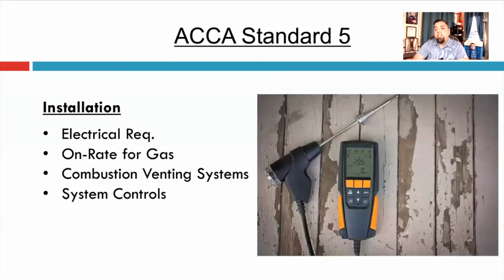Also, on the installation side, you're going to have to make sure you meet the electrical requirements. So you're talking about line and low voltages, measuring amperage, meeting wire size gauge requirements, grounding the condenser. Yes, that needs to be meeting the NEC, okay, is really important.